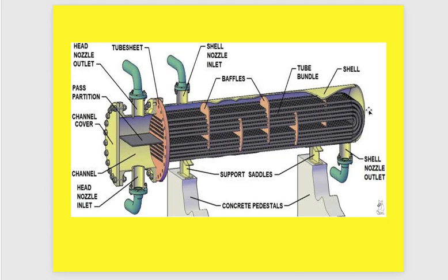So the advantages of selecting this type of exchanger are: it handles large thermal expansion, lower cost than floating head, high pressure capability, and reduced leakage risk. Okay, suitable for severe services.